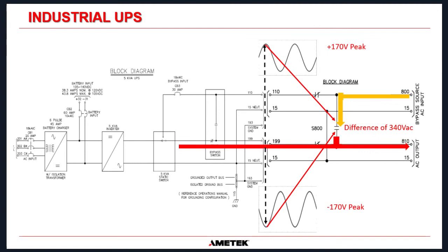So let's say, for example, the inverter output is not synchronized to the bypass supply. As you can see on the bottom waveform, when you are about to move that bypass switch, let's say you are at the bottom of the sine wave for the inverter output. But because you're exactly, let's say for this example, 180 degrees out of phase, the bypass supply is going to be at the top.